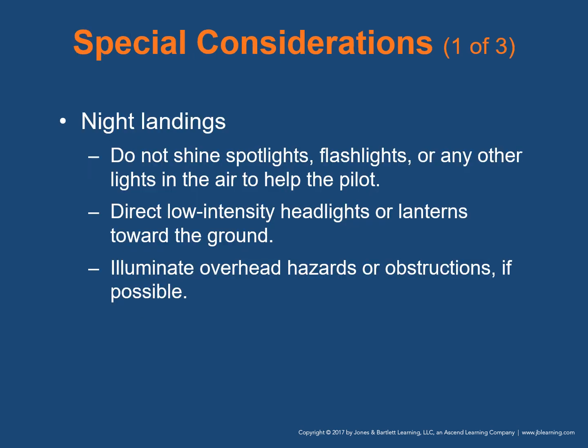Other special considerations include night landings. Do not shine spotlights, flashlights, or any other lights in the air to help the pilot, because they may temporarily blind the pilot. Direct low-intensity headlights or lanterns toward the ground at the landing site. Illuminate overhead hazards or obstructions if possible, if they're around, and make sure that the crew is aware of them.